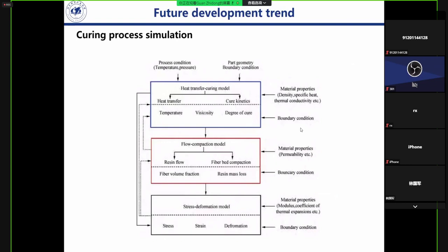Another hot topic is residual stress in composite processing, which is also very interesting to us. In our experience, the effect of process residual stress on composite structural strength is likely to be about 10%, and even higher for bad structural design and process. In this area, we first need to calculate the process stress more accurately and combine it with external force to determine the strength of the composite material.